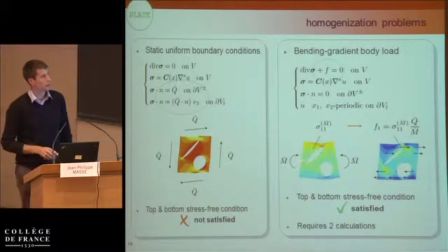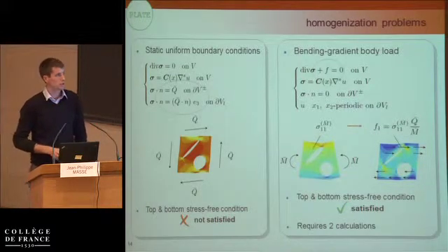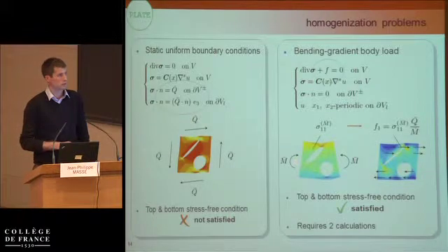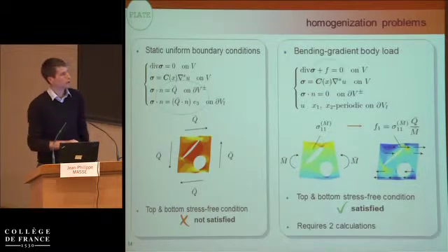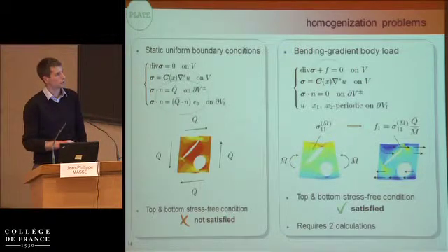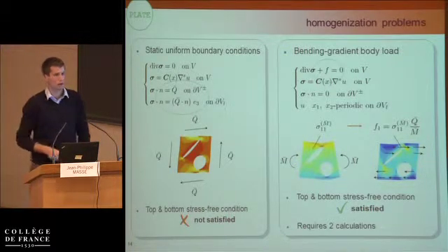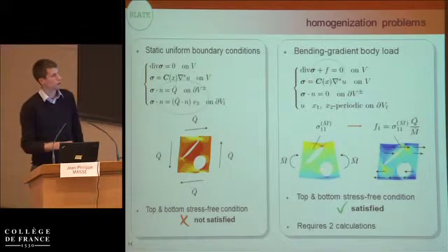Here we just compute the bending solution, applying a bending moment on the unit cell, and then we take the resulting stress and put it as a body force into the unit cell.